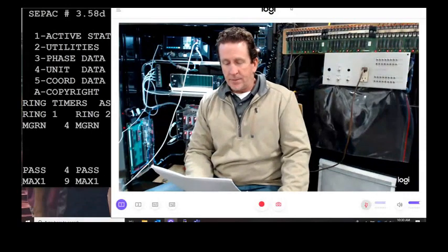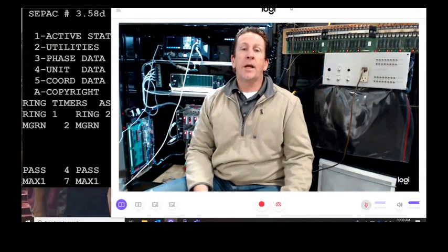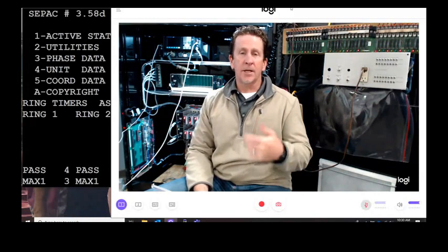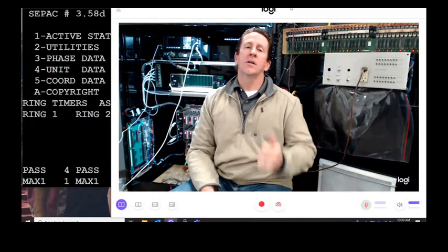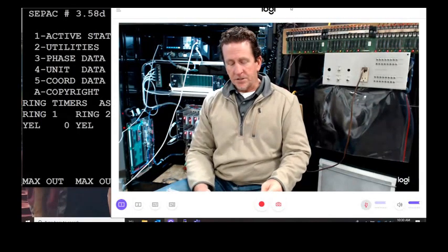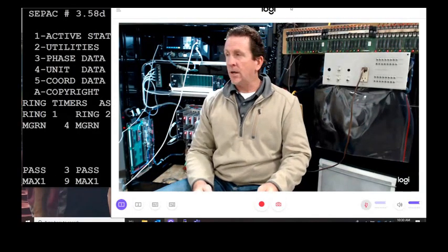All right, so that's the BIUs. With the BIU, you're going to look at the power light that's on and the transmit receive light, and make sure that's all going. If that's not going, then that's going to pinpoint us in a direction. I just covered the SDLC cables.